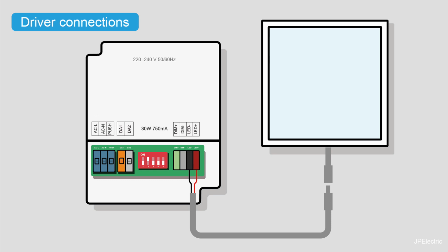This is where you need to confirm with the manufacturer what they mean by mains dimming. It'll push dim, but it won't accept triac dimming. So we need to check the compatibility of the dimmer, the driver, and the lamp. 1 to 10 volt and push dimming are one of the most basic and simple types of dimming method you can get for these LED panels. DALI and such, more complex.